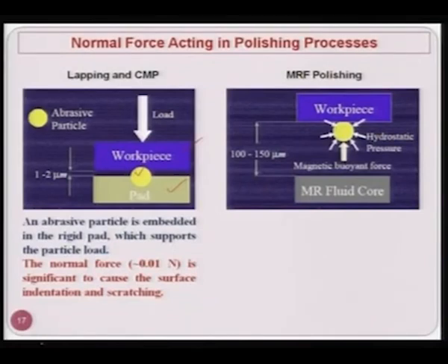But if you see the MR polishing phenomena, here the workpiece is in contact with the abrasive particles, but the abrasive particle is not in contact with any solid support; rather it is a part of the MR fluid, and the force being applied on the abrasive particle is through hydrostatic pressure and magnetic buoyant force.